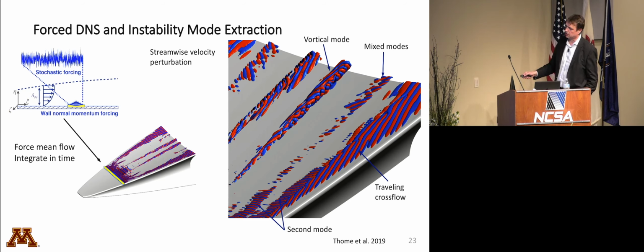This high-frequency stuff is clearly second mode, and interestingly, you can see that it dies out, detunes from the boundary layer, and then something happens, and it gets this additional modal response that takes place here that has some kind of obliqueness to the flow. So it's possibly some kind of cross-flow type of instability. We don't really know yet.